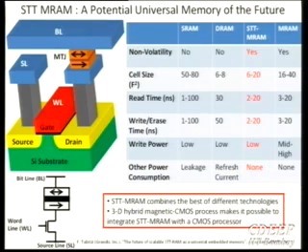I still need one transistor, and so the area of this magnetic tunnel junction turns out to be about 10 nanometers by 10 nanometers by 10 nanometers or so. If you're looking at 130 nanometer technology, or a 65 nanometer technology, your area is still dominated by the area of this guy. And it turns out that the MTJ structure is quite scalable. If you scale it down, the write current requirement is going to go down. I'm not talking much about the write current requirements at this time. It's still pretty high, but way better than MRAMs.